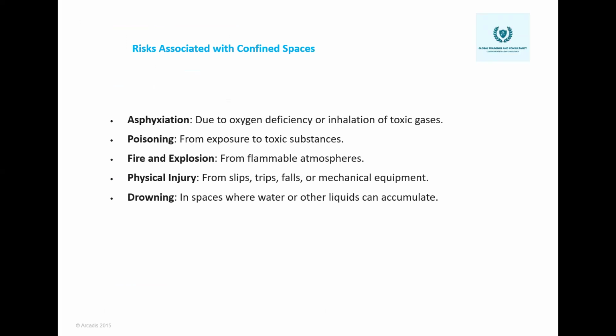The risks associated with these hazards are asphyxiation due to oxygen deficiency or inhalation of toxic gas, poisoning from exposure to toxic substances. Substances are the materials, gases, etc., even the liquids. And physical injury from slip, trip, falls, or mechanical equipment, drowning in spaces where water or other liquids can accumulate. As I mentioned, the manhole is one of the examples of a confined space.